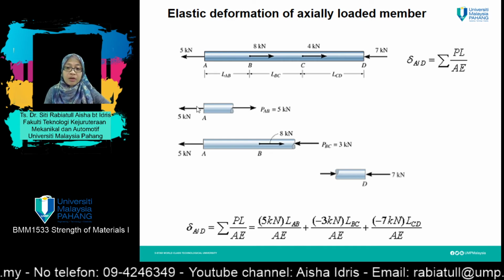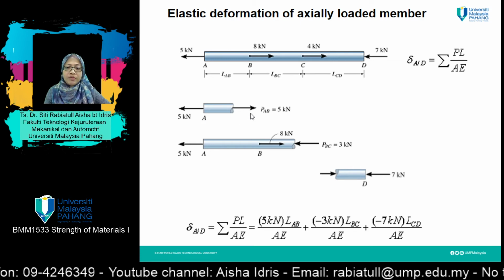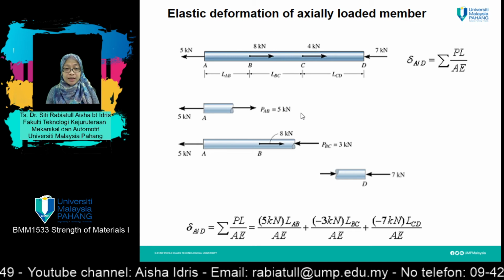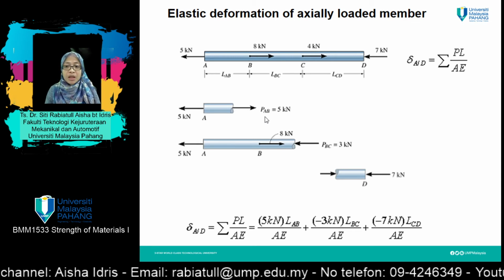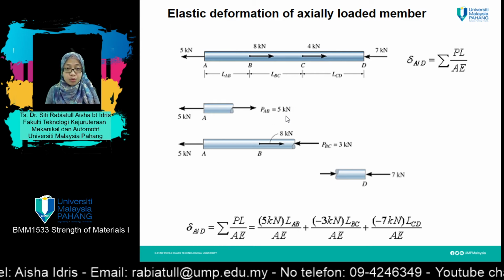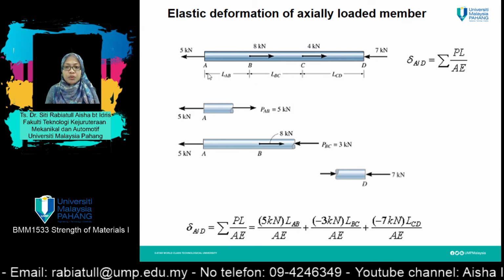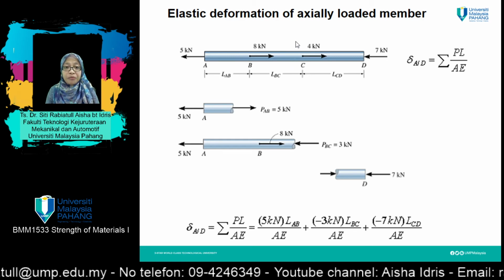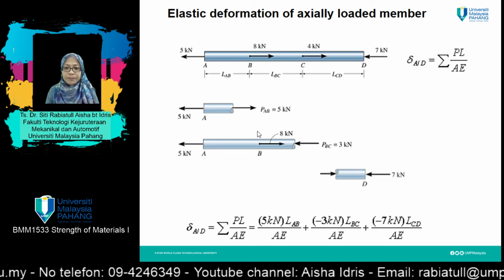structure. From there you need to draw the free body diagram. After that, you take the total forces in the x direction equals 0. Then you'll get the value of PAB, which is equal to 5 kilonewton. After that, you cut again from point A until exactly before point C, so you will get this structure.